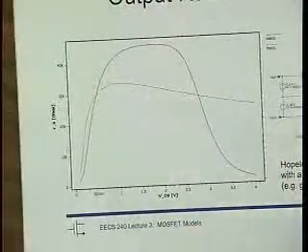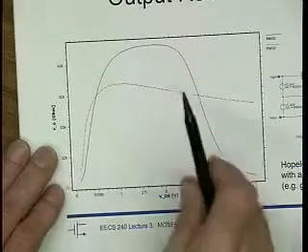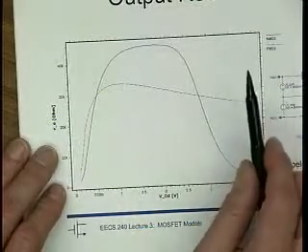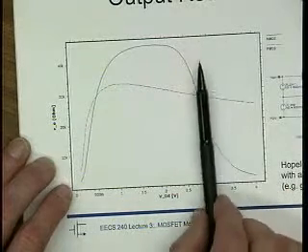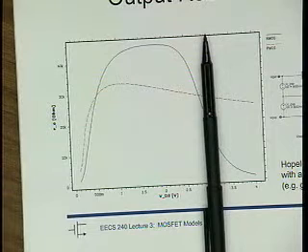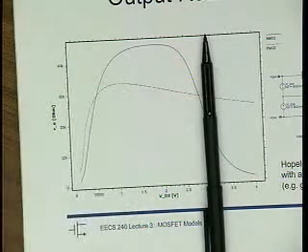And of course, technologies are designed and transistors engineered so that this occurs as close as possible, or actually beyond the supply voltage. So for the PMOS, that's pretty okay. For the NMOS, well, this is 3 volts. So definitely, if we put the full 3 volts, the full supply across our transistors, the R-out's going to suffer. Okay. So, anyways, I mean, go and describe this with lambda, right? I mean, forget it. It's lambda business, just not very useful.